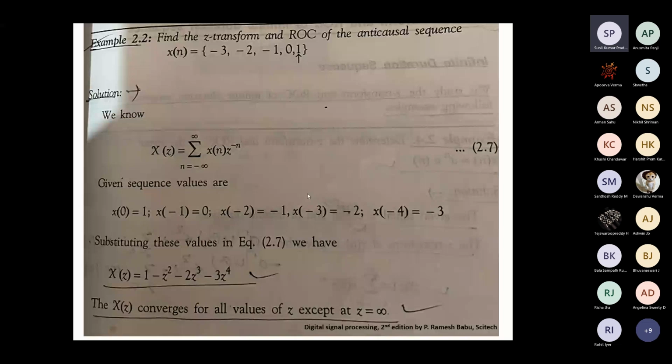Then we discuss this kind of signal, which is an anti-causal signal. For anti-causal signals, it is a discrete time sequence. So what is your X(z)? This is your X(z), and what is the ROC? It is for all z except z equal to infinity. So remember that for a left-handed sequence, also called an anti-causal sequence,